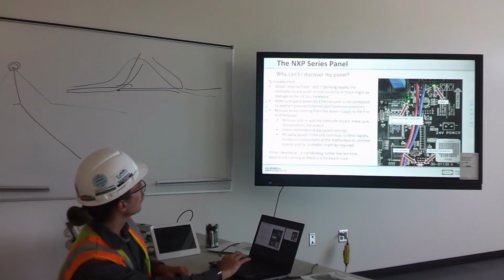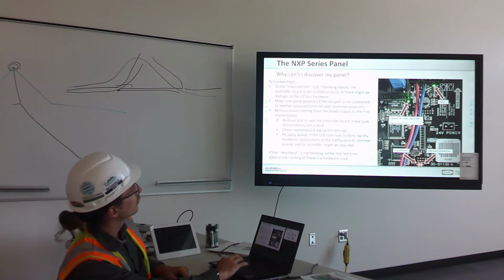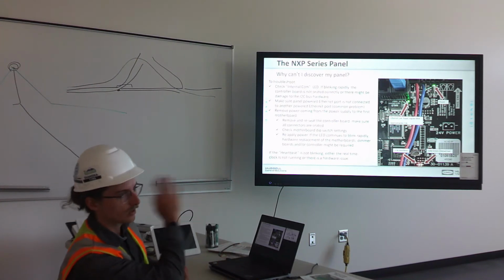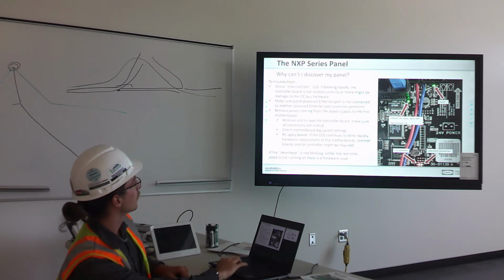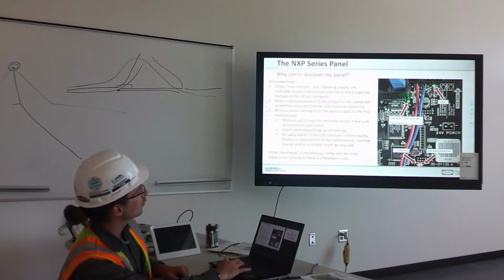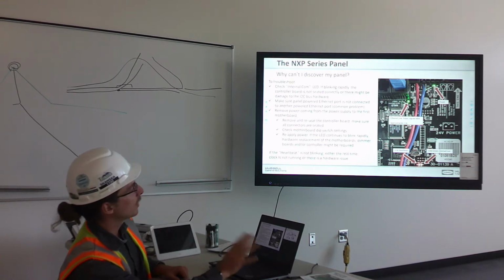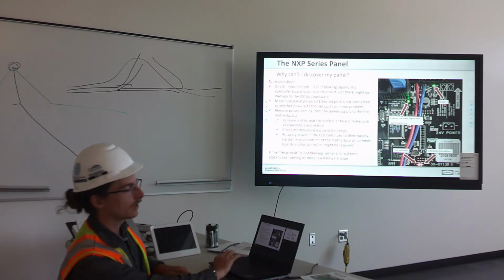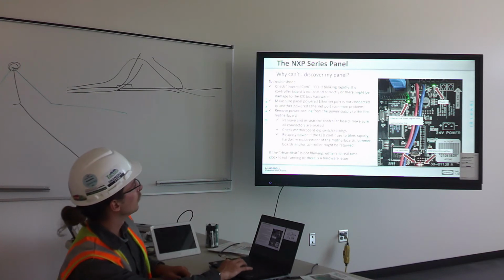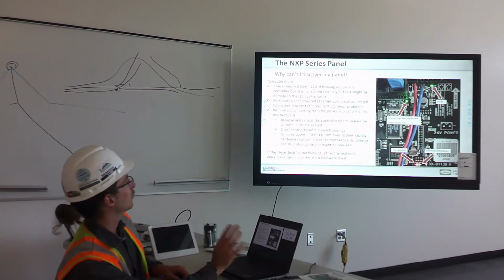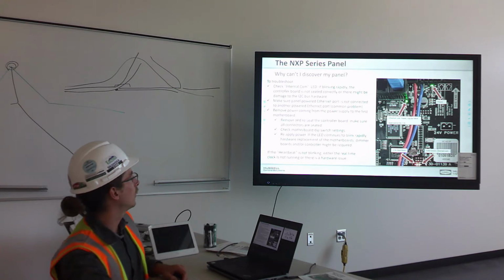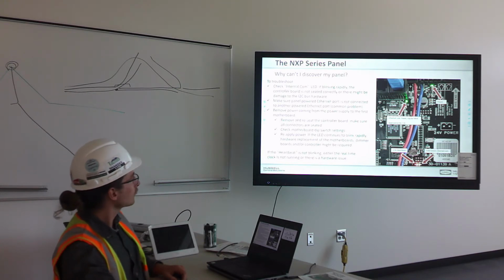So these are your 2 network ports. They've got that green light similar to the bridge that tells you that it's talking to the other end of that wire. You should see this red LED doing a 1 hertz flash. That's telling you that panel's operating normally as it should. And then you've got 2 solid green lights that also indicate normal operation.